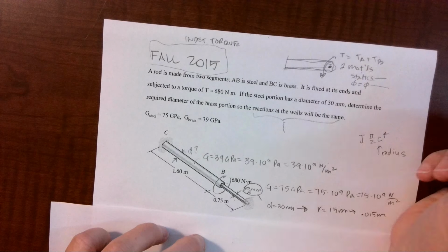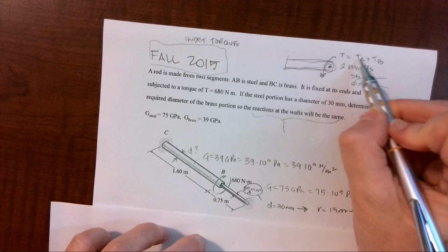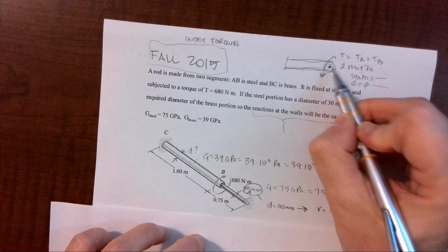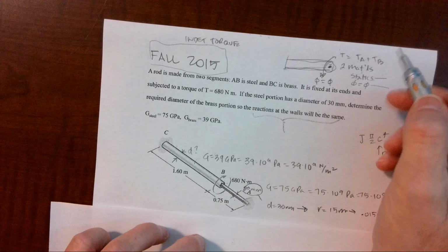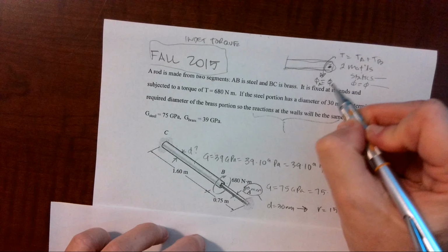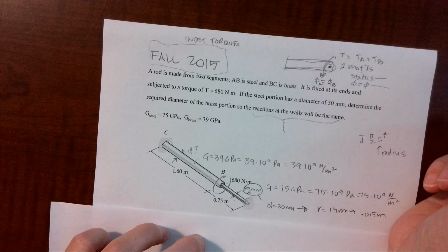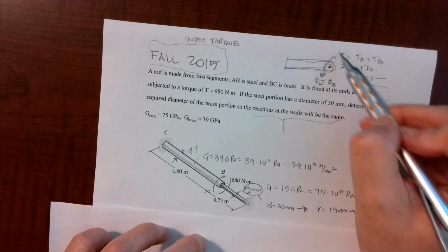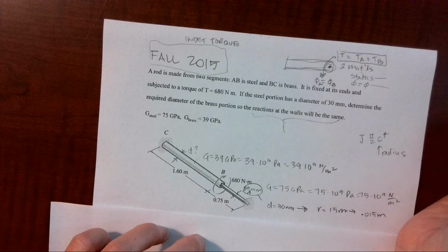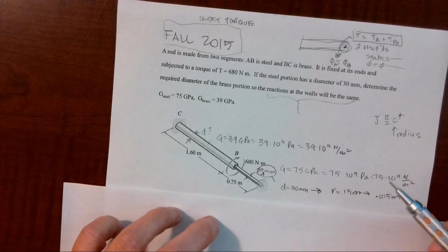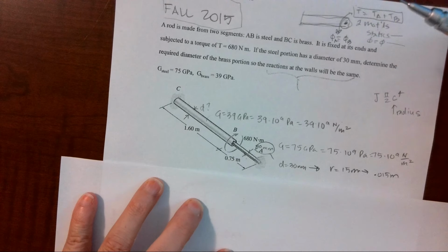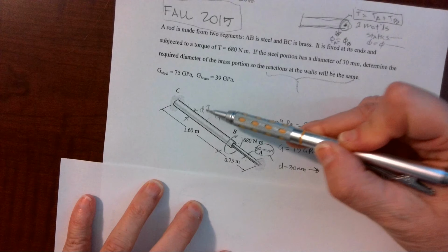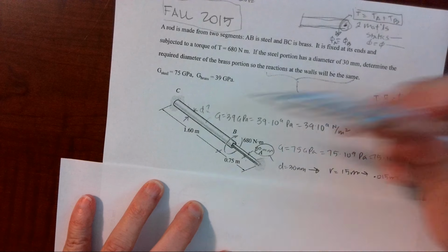So statics would have started T equals TA plus TB, and then I would have known that phi at the end from material A had to equal that phi of material B. Okay, it's the same concept. You always start here. When you see that you have more than one unknown, it tells you that you have to move into indeterminate. Now this one is worded a little bit differently because we want to go back and find what the diameter of B to C is.